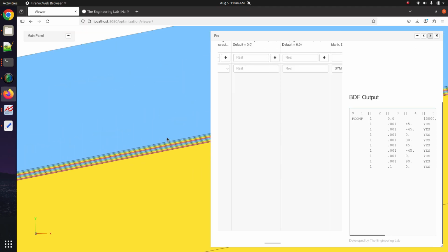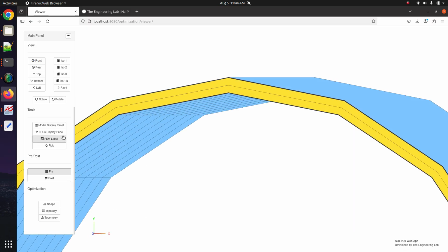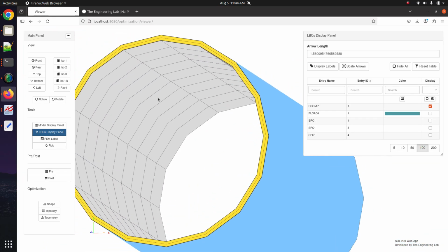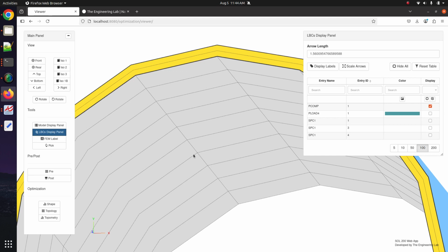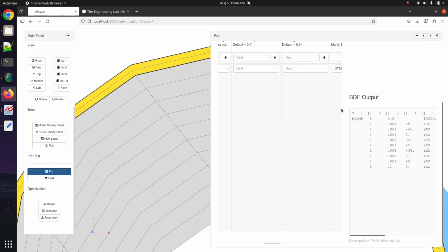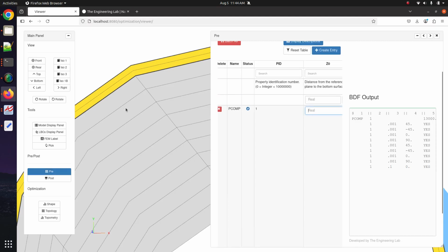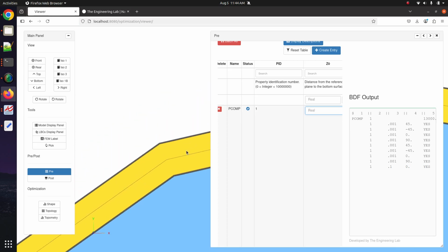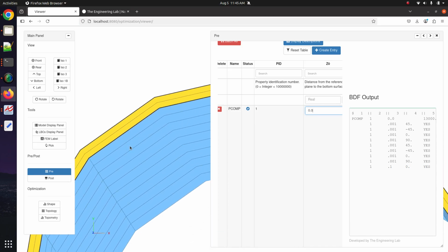We'll do an analysis in a moment. Let me do this. Oh, right. So okay, perfect. So these are 2D elements, and then our laminate is on top of the 2D elements. Sometimes the 2D elements are used to represent the outer mold line. So that's why sometimes it's good to experiment with that Z0 option. So this is the default. When it's blank, this is what it looks like. So the laminate, the 2D elements are in the middle of the laminate, but if we say use an offset of 0, then it puts the laminate on top of the 2D elements. So the Z0 will depend on what your application is.